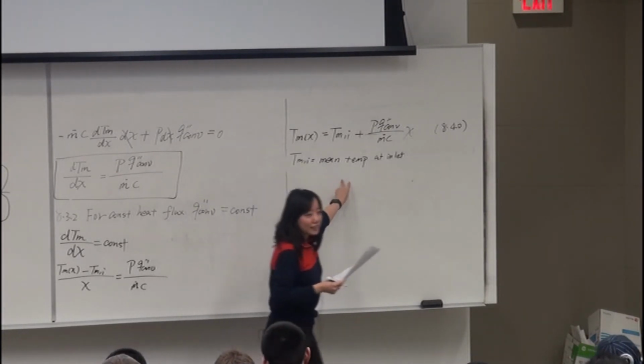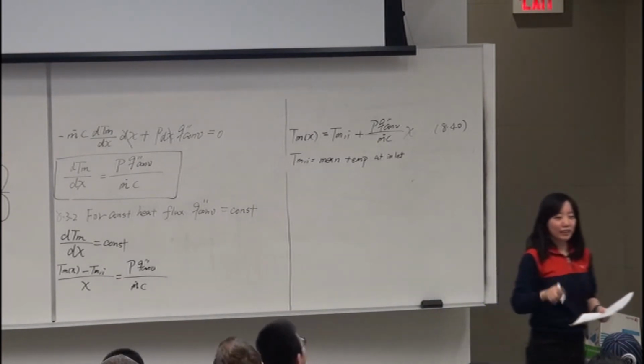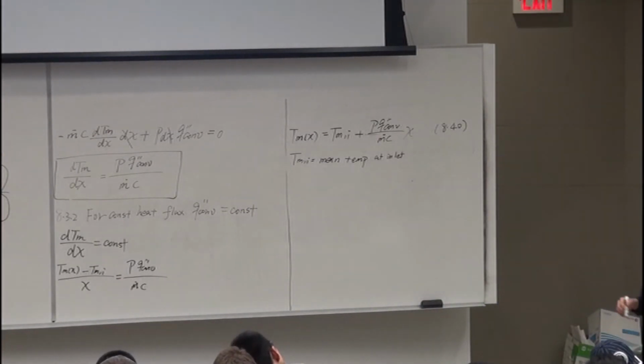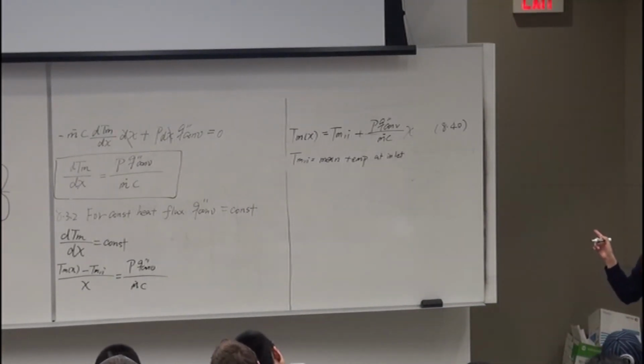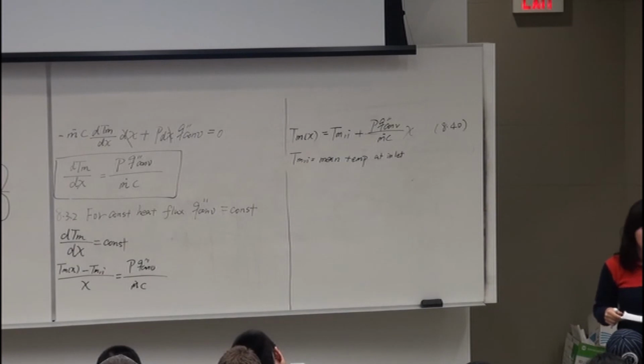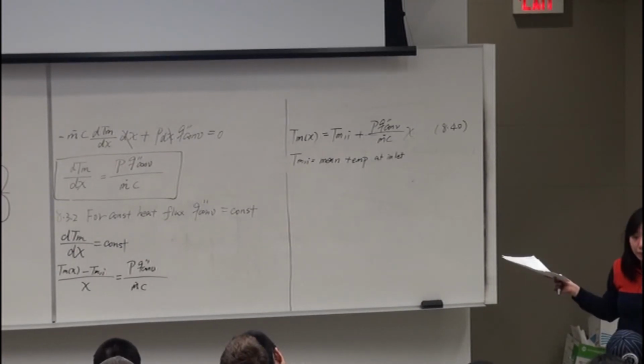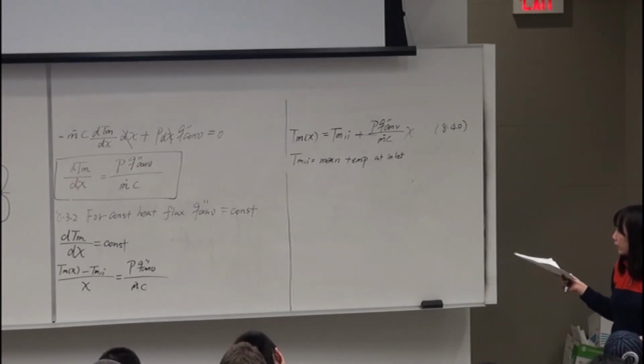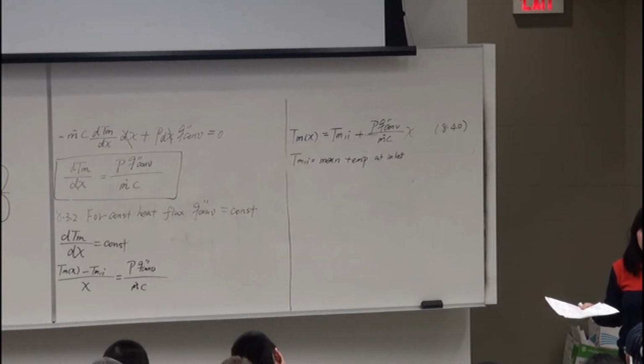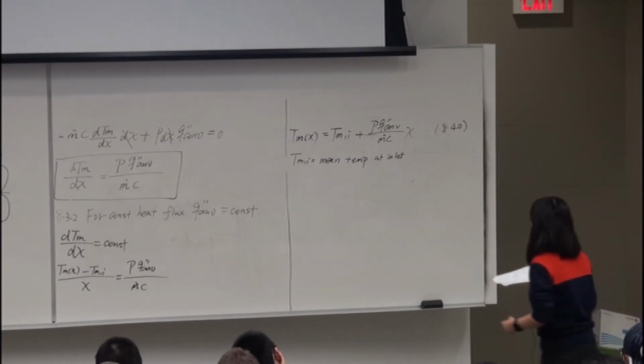This is super classic. The book solves the entire differential equation to end up with equation 8.40. But we utilized what we were taught in the first class, energy rate balance, and we understand the heat transfer mechanisms inside, advection and convection.